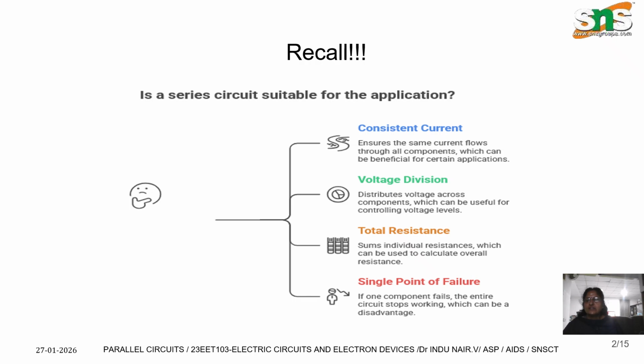A series circuit has all the components in one loop connected by wire, so there is only one route for the current to flow. So in series, the components are connected one after the other. It is called cascade, or a one-to-one connection. So the same current flows, but the voltage dropped across each element will vary.